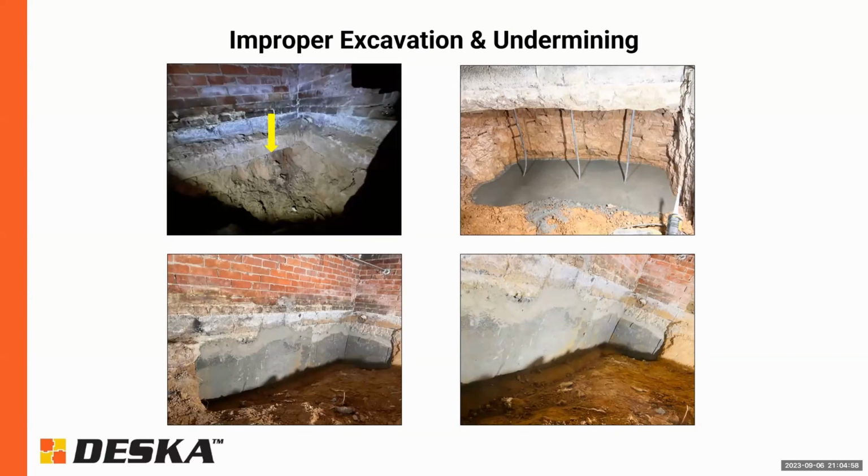So this is an example of what we call traditional underpinning, where essentially you excavate below and you install a concrete footing below. Assuming there's no settlement, no damage caused, or no movement, you can essentially carefully, with temporary bracing and in a sequenced phasing approach, excavate and install a new footing below.